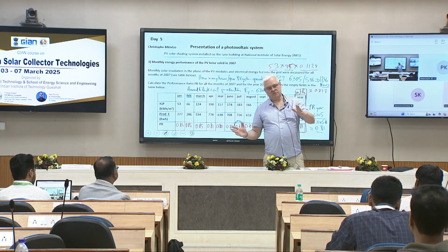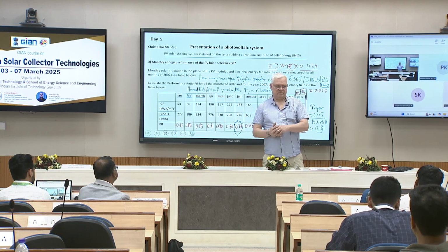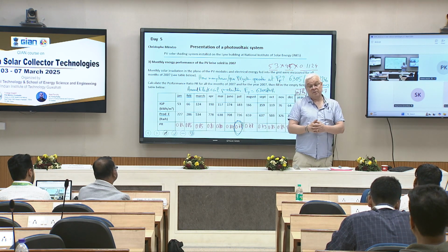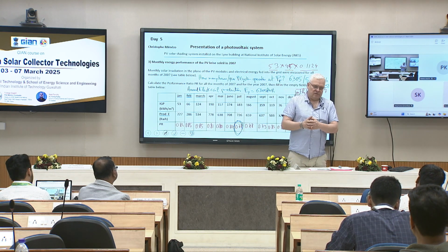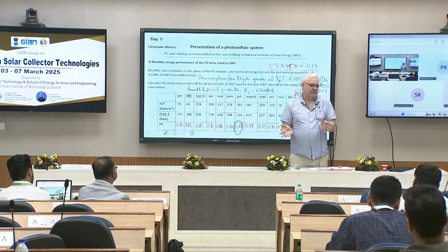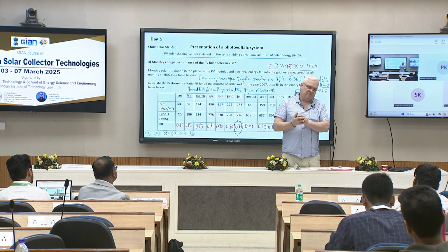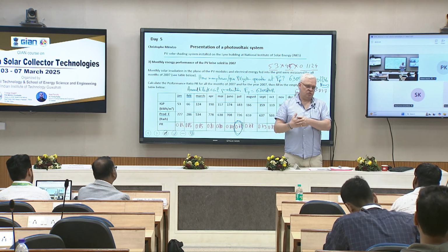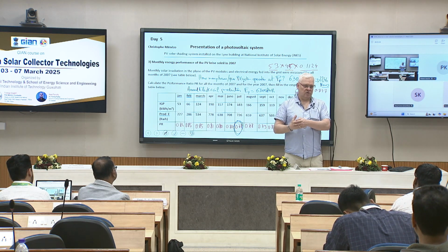So the performance ratio characterizes the operating condition of your PV plant, whether it is well or not. It is important that it's good: if it is over 0.8, 80% is good, so no problem. You don't have to check every day if you find that it's good. If it is below, you should investigate the reason why.